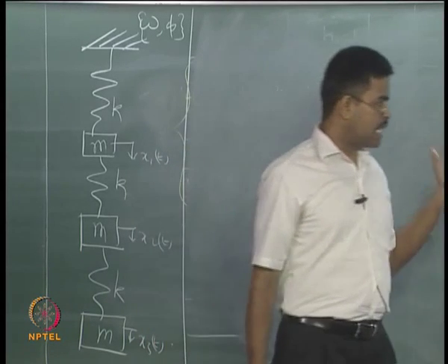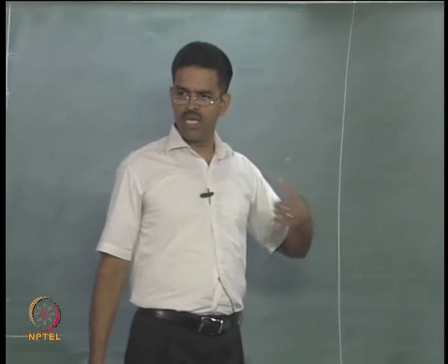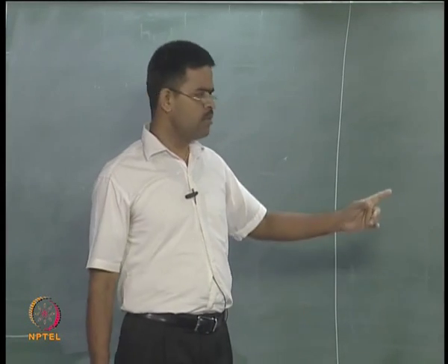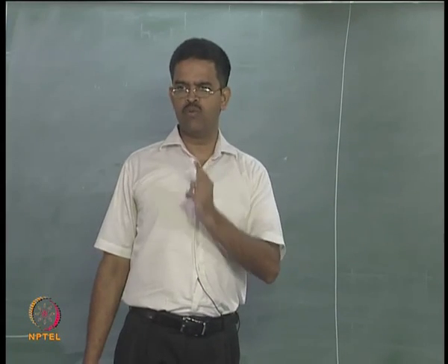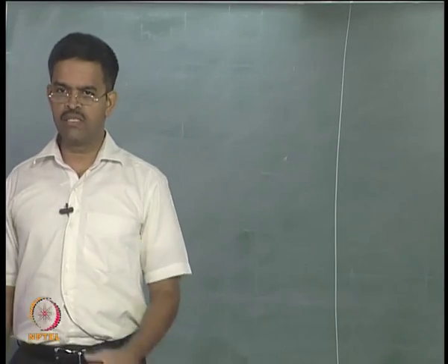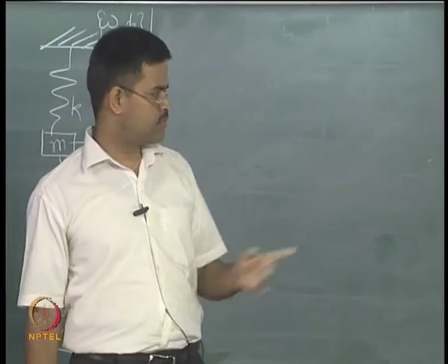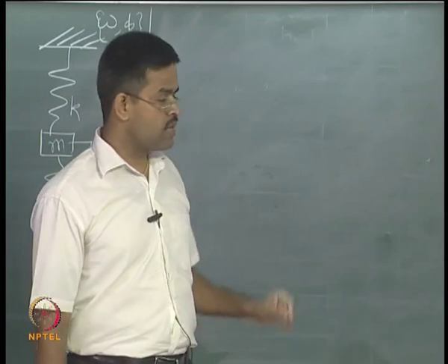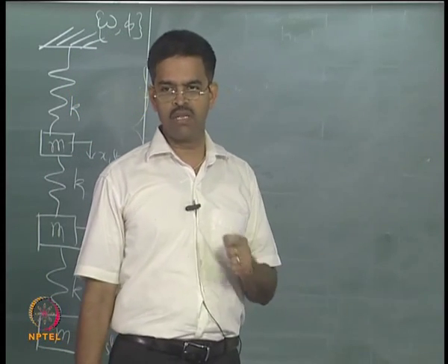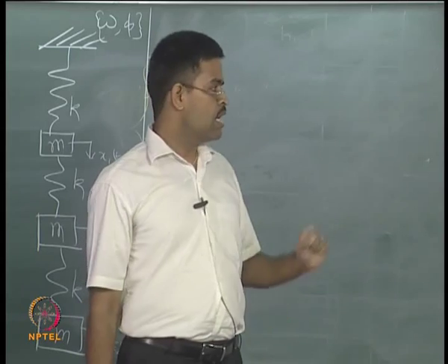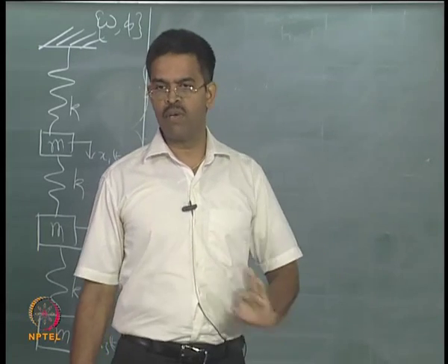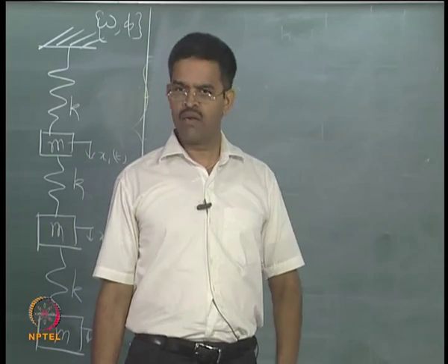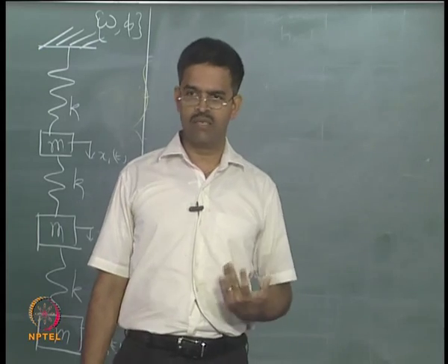Now, by Dunkerley and Stodola's law, you have an n degrees of freedom problem. You will be able to easily do at least one frequency and mode shape by hand and check whether the answers obtained in the software are correct, to an accuracy of about 5 to 10%. So, this is a very important stage in dynamic analysis: understanding that I must be able to solve all of them by hand first and write my own program, which is an analytical technique.